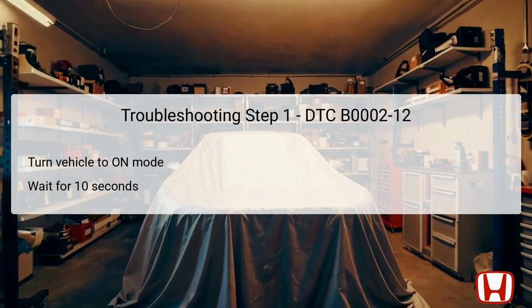The first step in troubleshooting DTC B0002-12 involves the initial confirmation procedure. This requires the technician to turn the vehicle to the on mode. It is essential to allow the vehicle to remain in this mode for at least 10 seconds. This step is critical as the SRS unit needs time to perform its self-check and register any issues effectively. The SRS unit monitors the condition of the driver's airbag system during this time, checking for voltage abnormalities.